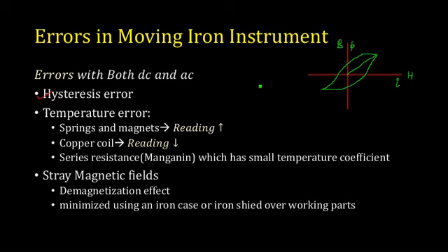Now in the case of a DC, what happens? Suppose you are measuring 5 amperes. Now you are changing the value of the current that is flowing from 5 amperes to 6 amperes. During this variation your flux density varies, so you will have a change in the flux density. You will have a continuous variation of current, and also a continuous variation of flux density. That variation of flux density will be affecting the readings. So you have such errors happening in the system.